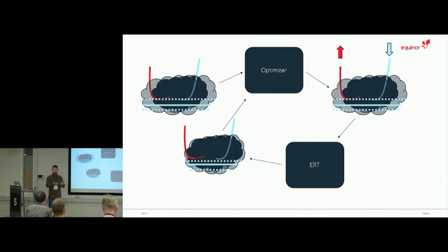So that's this thing of having this uncertain model, sampling multiple models, then simulating all of those into the future, comparing that simulation data with what we are observing, and then using these Kalman filter equations that we saw used on the train example, but the full ones, and then get a better estimate of these parameters.